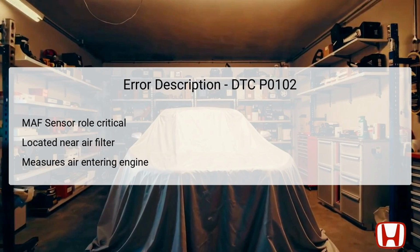When the vehicle's engine management system detects that the voltage in the MAF sensor circuit is lower than expected, it triggers DTC P0102. Such low voltage signals typically indicate either a wiring issue, a fault in the MAF sensor itself, or a fault in the power supply to the sensor.